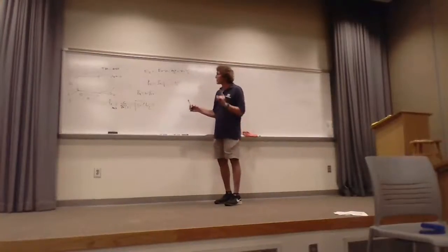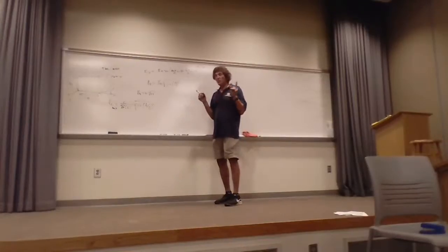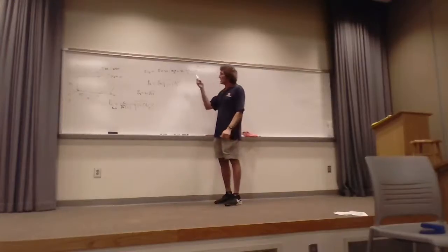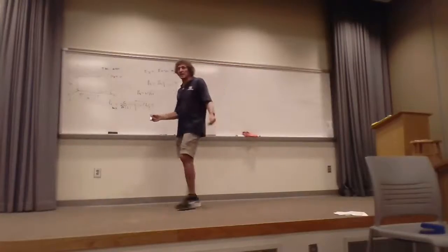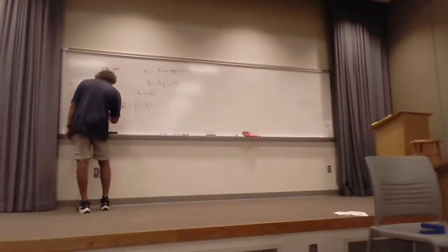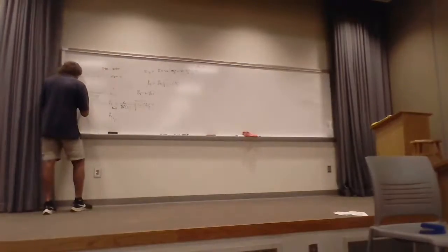Now, this is important. That EZ value, not really important. It's important you know there's no HZ. If it's called a TM mode, it means it's transverse magnetic. There's no magnetic field in the direction of propagation. That's what it means. Everything's transverse, or perpendicular, to the direction of propagation. The lowest order mode, or the lowest frequency that can be carried in a TM mode, is FC11. So 1,1 is the lowest mode.